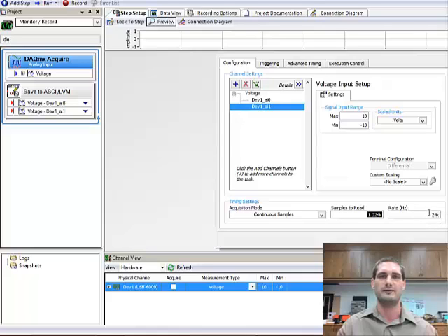So this was one bottleneck of our design, as we had to be able to down convert our received signal to at least below the Nyquist sampling rate of 12 kilohertz. We shot for between 2 and 6 kilohertz because we didn't have a phase lock loop, so we had to fine tune the VCO.